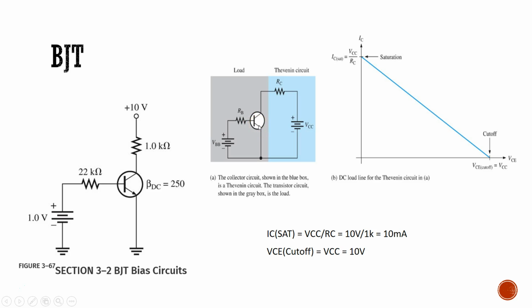If you've never created an open and measured things and done a short and measured things, I would suggest trying to safely do that because it's really fun. I'm pretty sure there are some examples out there of how to safely create an open and a short in a circuit and make the measurements. The best way to do it is in Multisim, because you can go into each component and create a fault, either an open or a short, and then make the measurements and see what happens.